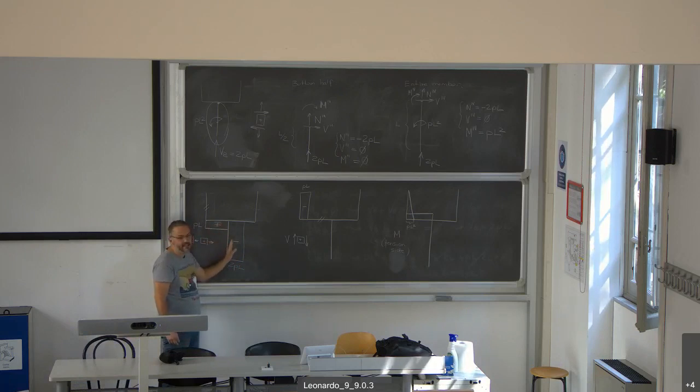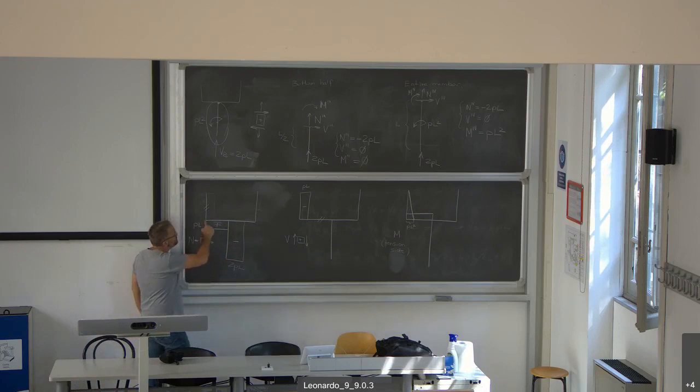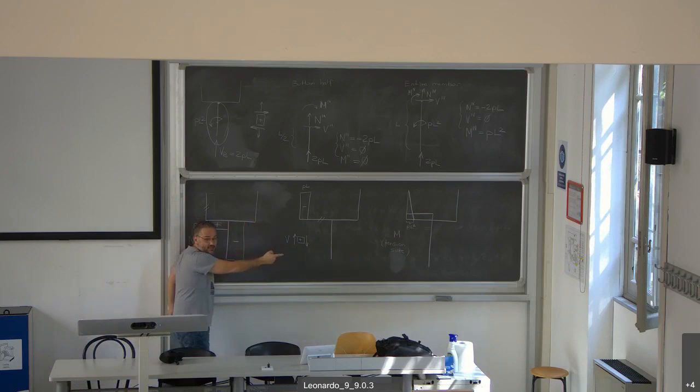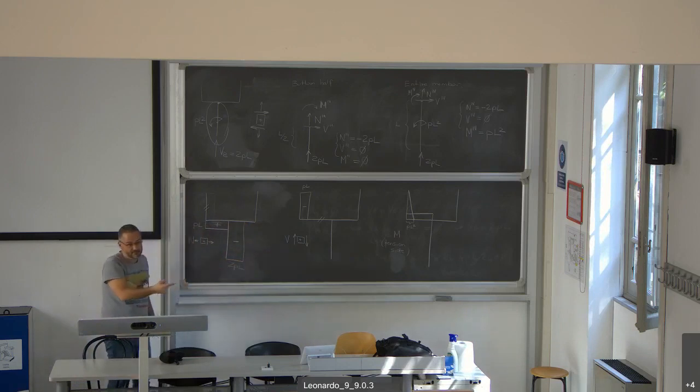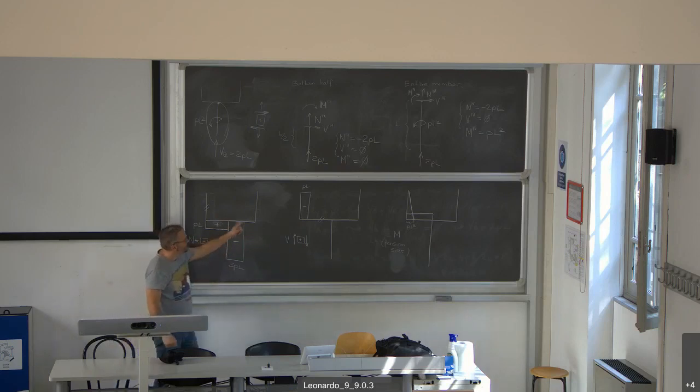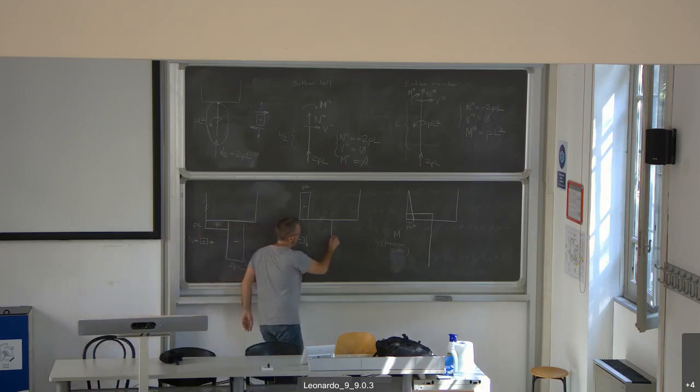Here I plotted negative on the right. So it really makes no difference. The important thing is to be consistent. So once I decide that positive on a horizontal member is down, the same should take place on other horizontal members. Shear V is 0.